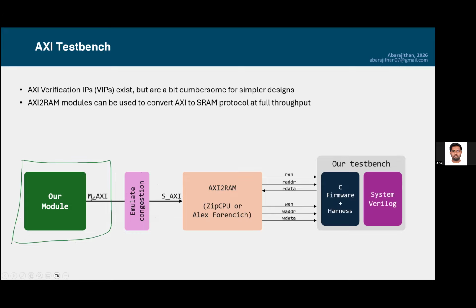So our module has a manager port, which means it wants to write into memory and read from memory, DDR, right? So you have to write into DDR and read from DDR. That's why you have a manager port. What you do is take this manager port and connect it into an AXI to RAM module.